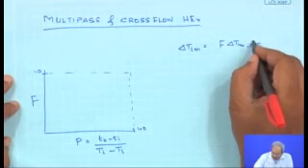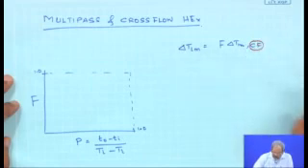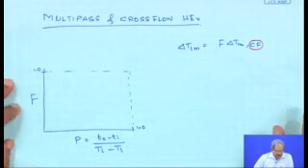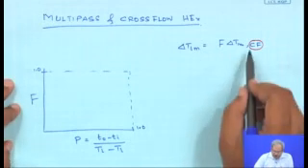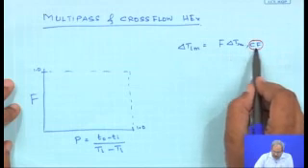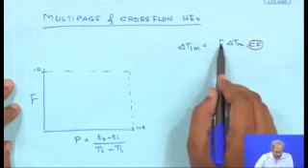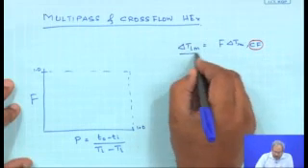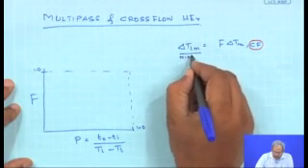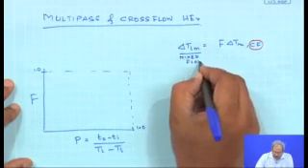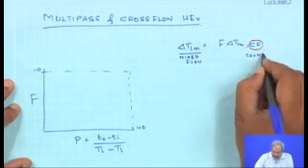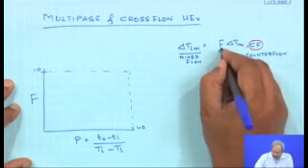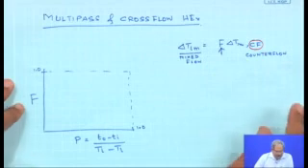This is important: you first calculate delta T LM as if the flow is taking place in counter flow, and multiply that with F in order to obtain delta T LM for the case of mixed flow. So this is for mixed flow conditions, this is for counter flow, and this F is the correction factor to be used.